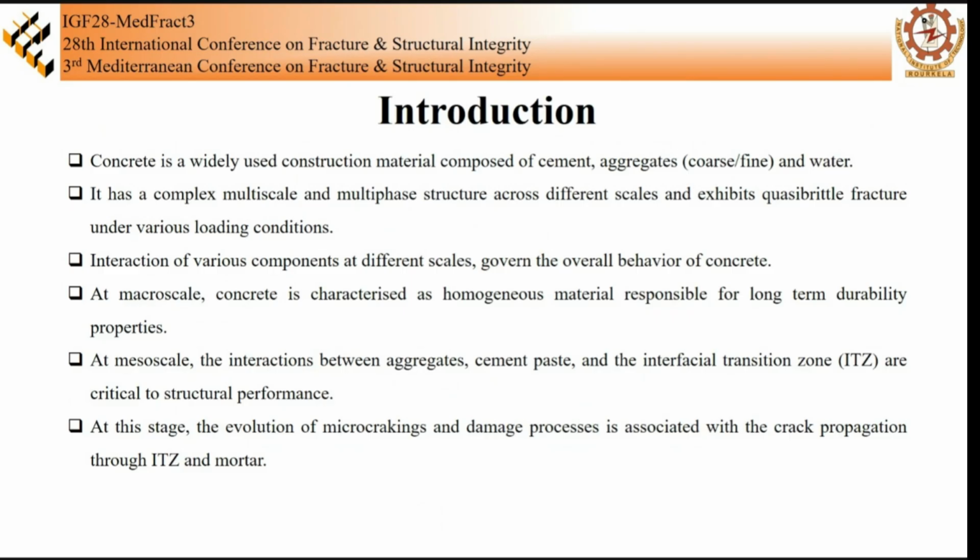Moving down to a slightly lower length scale, at the mesoscale, the concrete can be classified as a three-phase material. At this stage, the evolution of microcracking and damage is associated with the initiation and propagation of cracks throughout the mortar region and the interfacial transition zone (ITZ) region, ultimately influencing the macroscopic behavior.